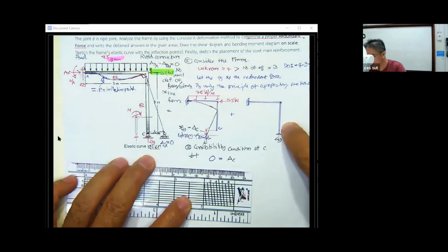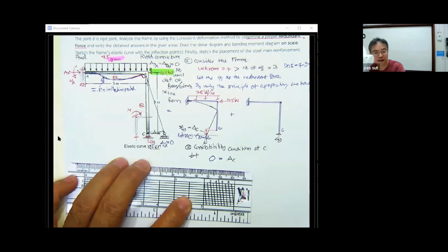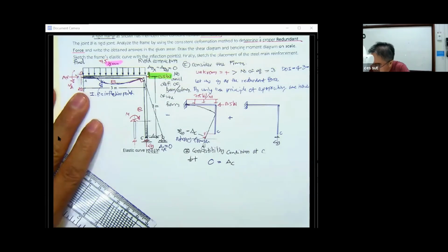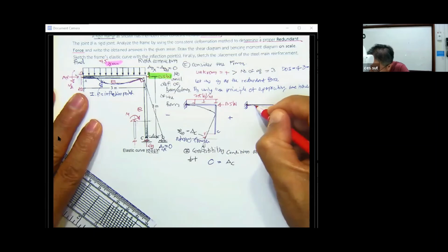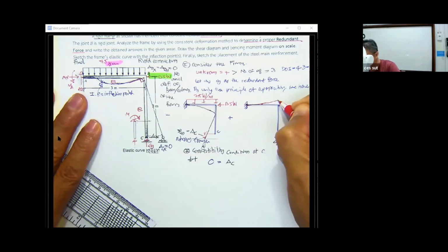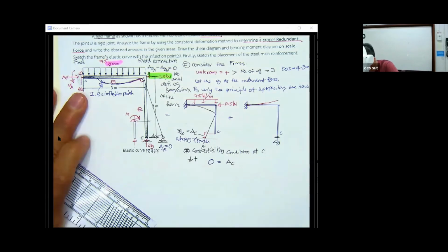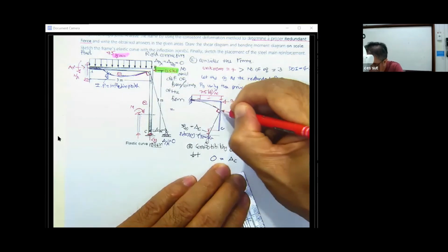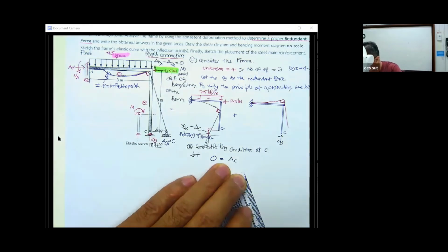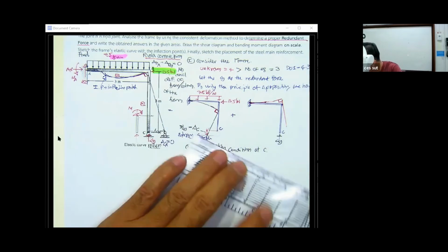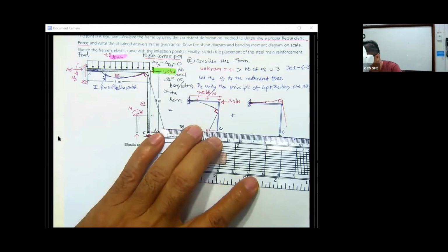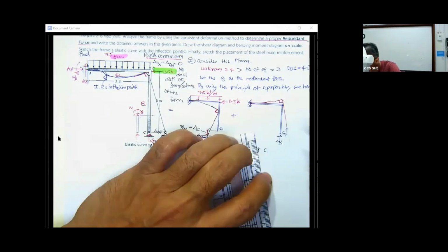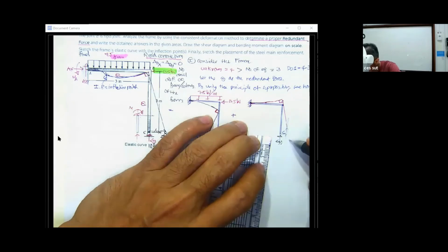And then coming into this, by doing this, you're going to push this frame, passing to this column, and then the frame is supposed to deform like this. So I believe under the application of this, this one, as I showed, is going to have this kind of deformation. And the angle here must be kept at the right angle, since it's a fixed connection, or a fixed joint. And again, the deformation of this can be considered in this way, and if you connect this one to this one, this is going to be the slope.